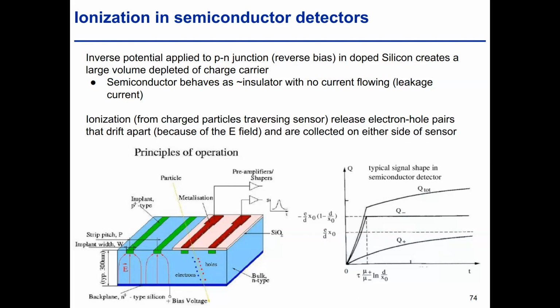We talked about gaseous detectors needing some multiplication. That actually also happens a little bit in semiconductors, close to the collection points, through different types of doping done around the implant. That multiplication is very limited, so the signal that you get is really tiny. What made it possible to use this as a detector, as we will see in a couple of slides, is having very sensitive electronics that can read out very small signals. Without that, you can't use this type of detector. But at a very high level, the principle is similar: a particle ionizing, and electrons and holes drifting.